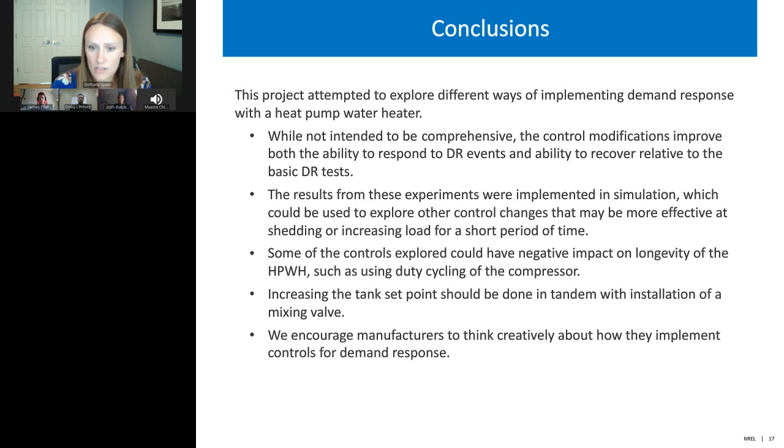A lot of these control changes would potentially have an adverse effect on the lifetime of the water heater, so that's definitely something to keep in mind. Duty cycling might not be good for the heat pump in the long term. Running super boost at 160 degrees F is also probably not great for the longevity of things and would definitely require a mixing valve. But I think the takeaway here is thinking creatively about how controls are implemented during these different events, and not just treating the events as changes in set point under normal operation. We might be able to get more demand response potential out of these water heaters and make sure that the consumers are happier with the results. So that's all I got.